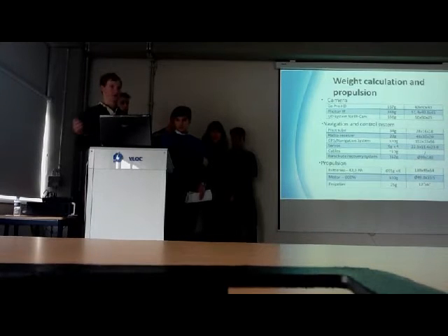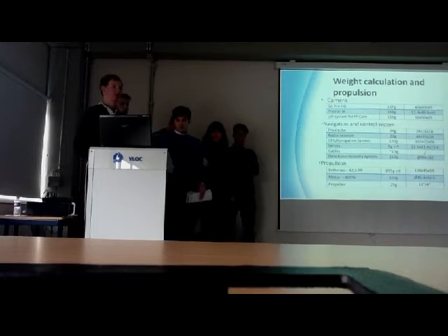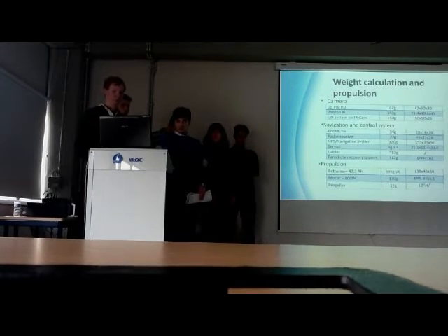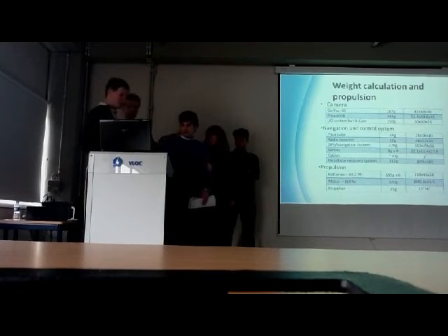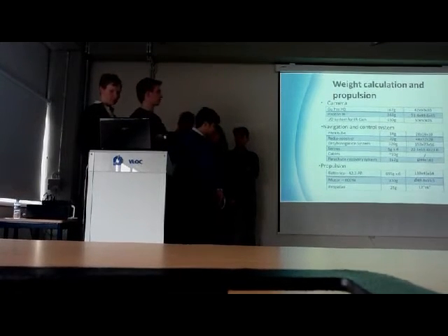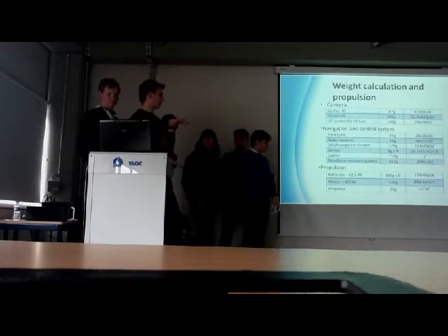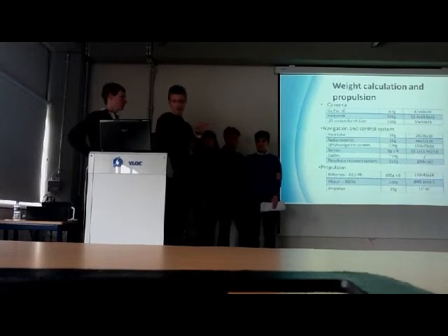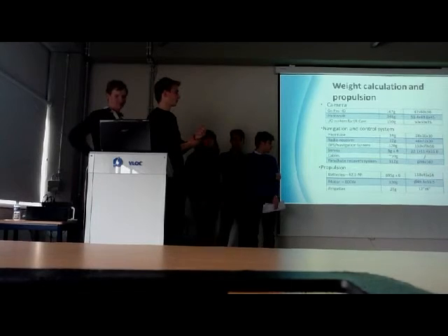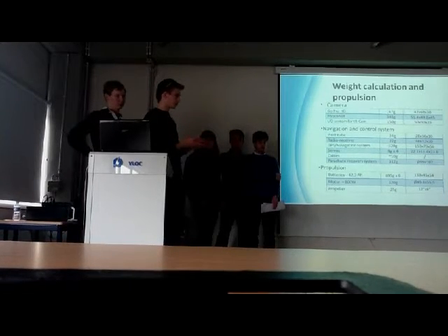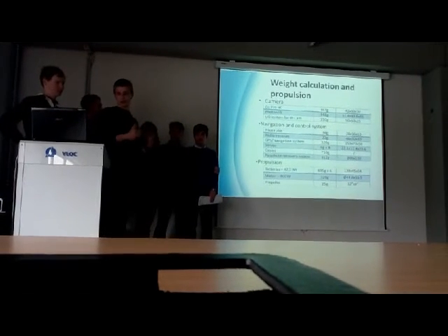In case there is an electrical failure, we can eject the parachute and are able to recover our UAV. For propulsion, I think Jakob. For propulsion, first of all, we approximate our total weight. It was about 10 kilos, and we use my model hobby experience that if you have a total weight of about 10 kilograms, you need about 3 kilos static thrust, and we choose